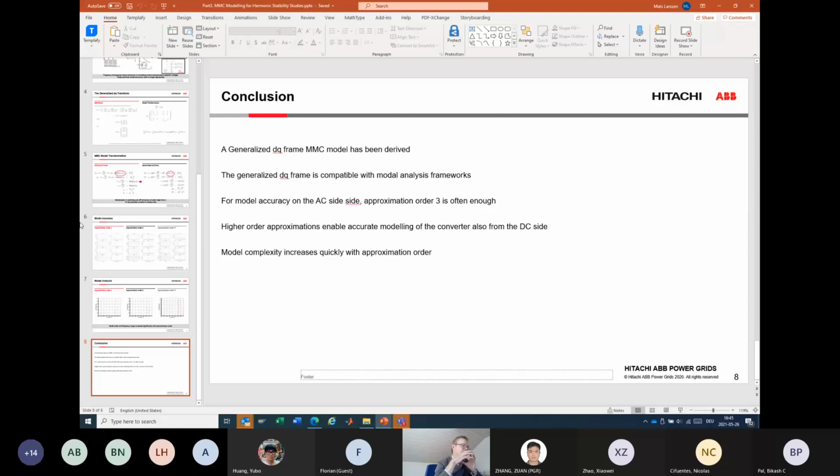And that has some effects at higher frequencies that you need to approximate with these modal analysis methods. I mean, and then single phase transformers will not perfectly decouple that also. That's the problem. Yeah, but I did not see that I got any particular limitation with relation to the MMC dynamics for that. It's more about the grid and whether the grid is symmetric or not. Okay. Because in the converter we have then controls that try to keep it symmetrical at all times.